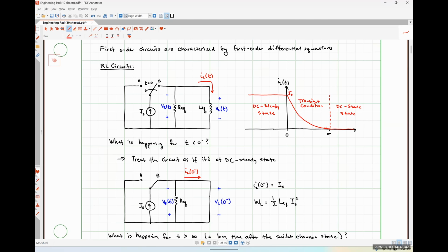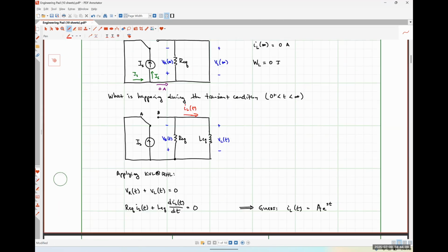So I'll go ahead and answer the question because I feel like I phrased it poorly and you guys aren't following me. Essentially, what's going to happen with the resistor voltage, at least during the transient condition, is we can just use Ohm's law and say that VR is just REQ times IL, right? So what we would observe